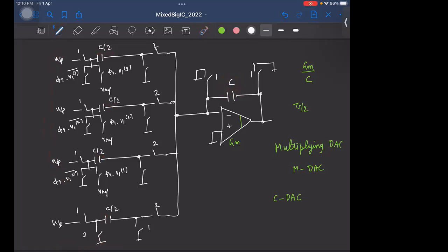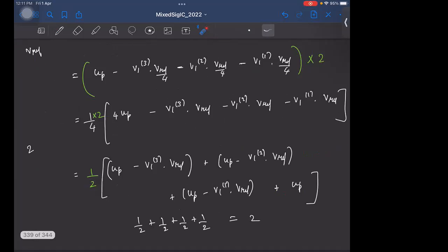okay. So for a 3-bit ADC, what will be the gain you want to realize actually? 4. And this gain is split into how many branches? 8 branches. So each branch should have a gain of half. Is that okay? I mean, you can take the same and rewrite also, you'll get the same.